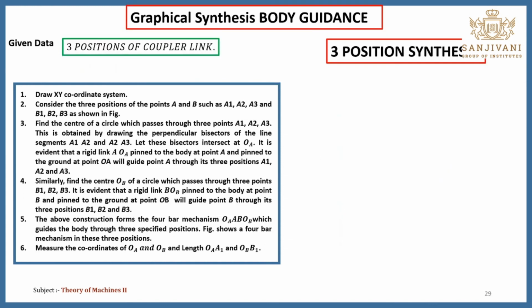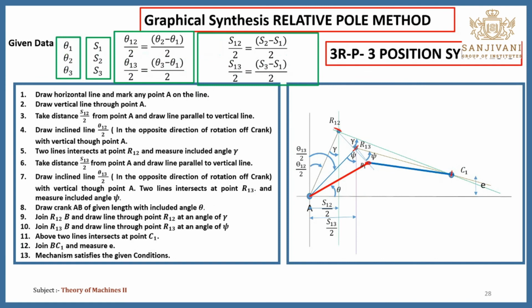And in this way you can do the synthesis of that slider crank mechanism. This is the offset slider crank mechanism using the 3-position relative pole method.